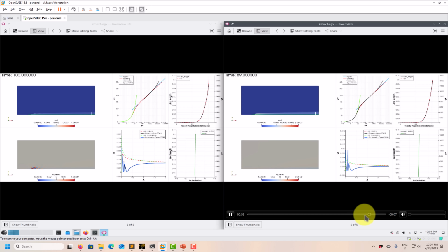So that's why the post-processing is very, very time consuming. I like to compare it with overset meshes, for those that know what overset meshes are. If you have worked with overset meshes, that is hell to post-process those simulations. Same with unsteady. So imagine overset plus unsteady is hell. Too much data, a lot of statistics, things to monitor, and sometimes you cannot get an idea of what is happening by having that data, and you need to keep running and running and running. So this is it, okay?